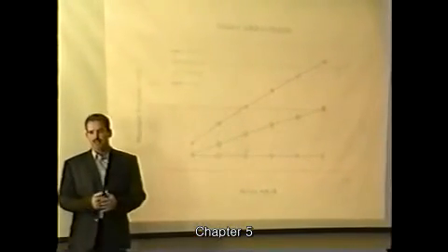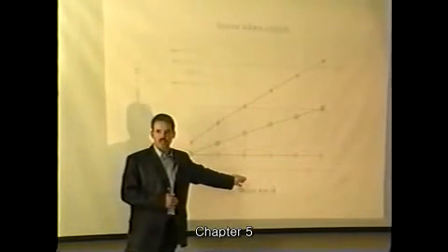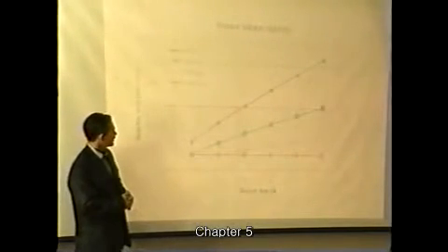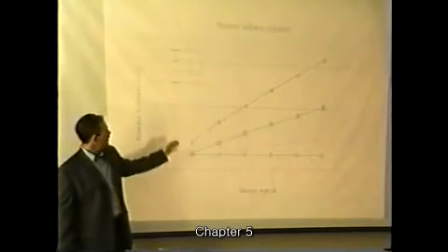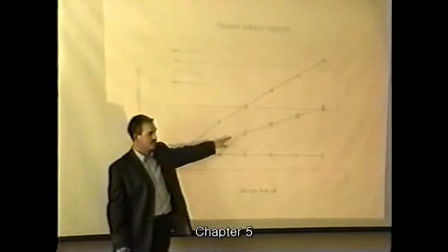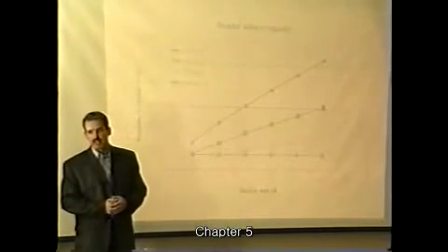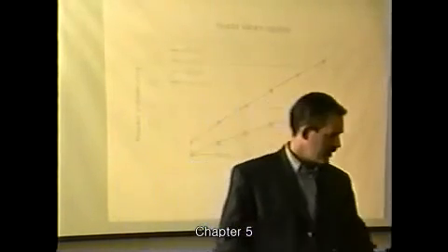And if you want any nitrification to happen, you would require almost 15 days sludge age. That's straight theory. They, on the other hand, were running the plant at 3,500 milligrams per liter, and they were not achieving any nitrification. So we were asked, could we achieve nitrification on that plant?